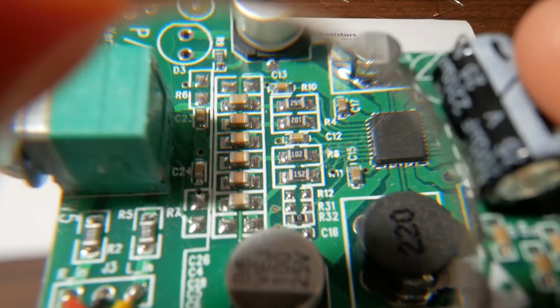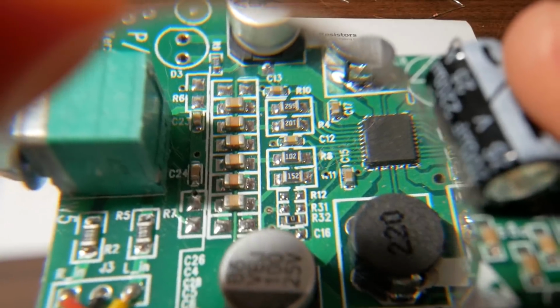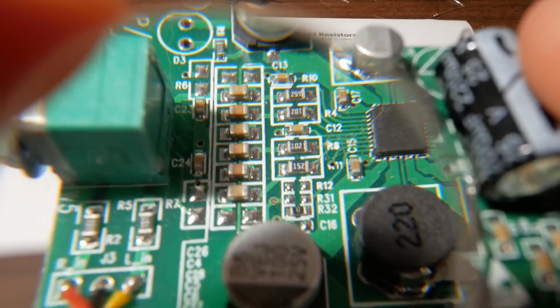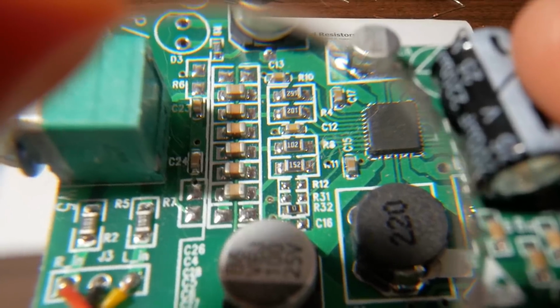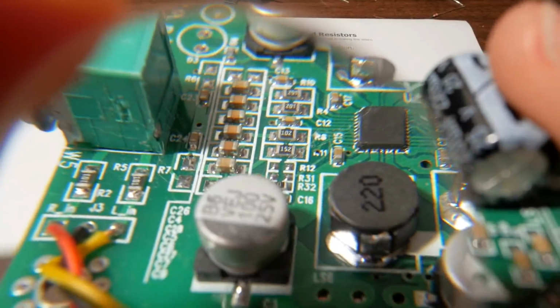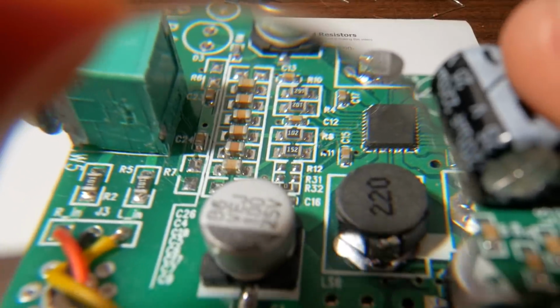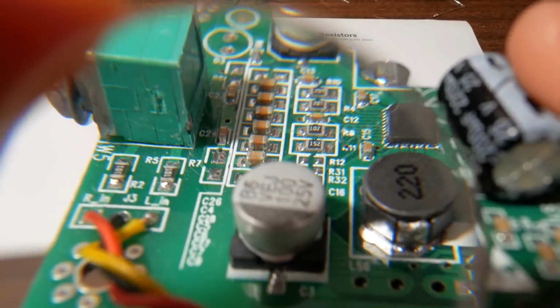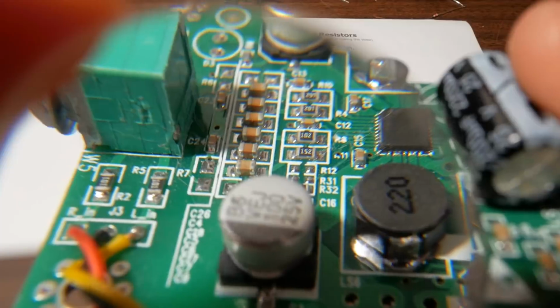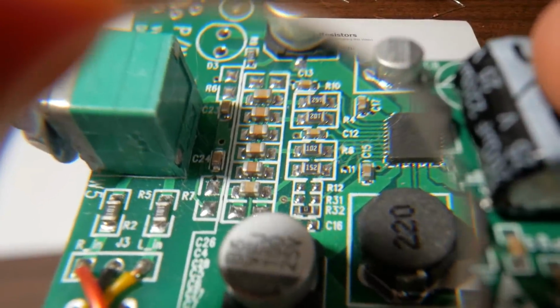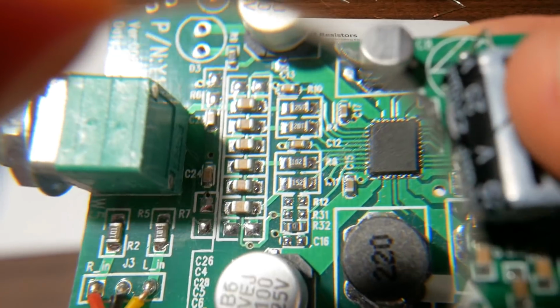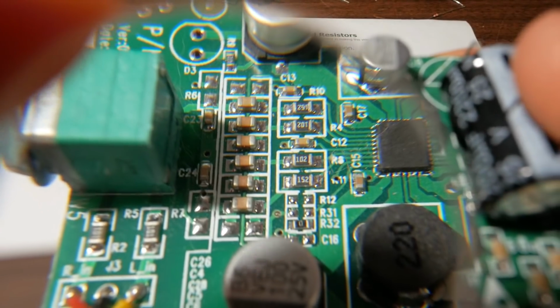So you can see there that one, the second up from the bottom, that says 102 on it, is a 1K resistor. And if you look at the side of it, you might be able to see that it's white on the bottom. That's the ceramic substrate, and that black area is the actual resistive part of it.